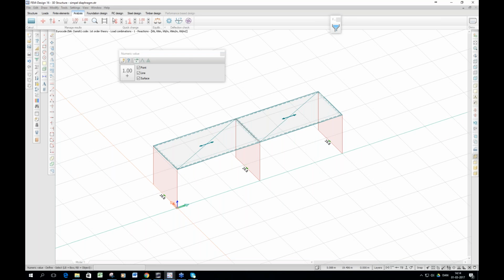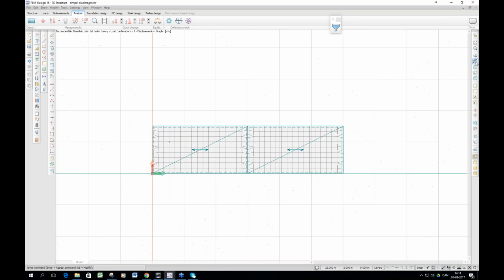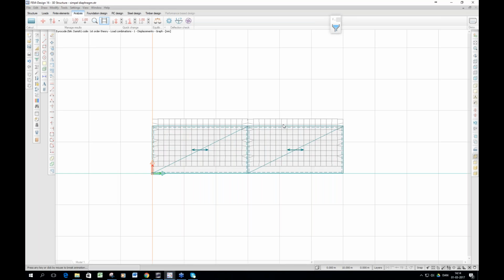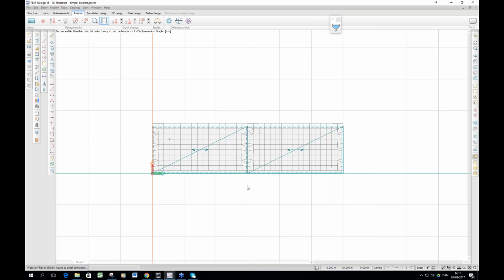So that you need to do as well to make sure that the hollow core slabs can transport it like this. What is interesting now is the displacement, and the displacement shows you very clearly what the diaphragm is. Look at it from above, and I increase like before. It shows like 1 unit movement, not the in-plane deflection we got from before, but like 1 unit moving infinitely stiff in plane. So this is the reason for the diaphragm.